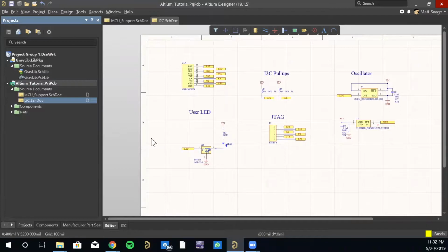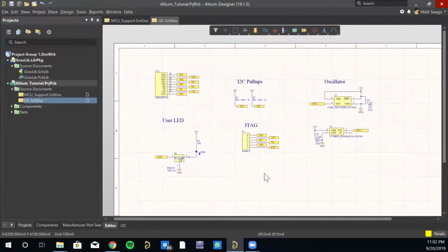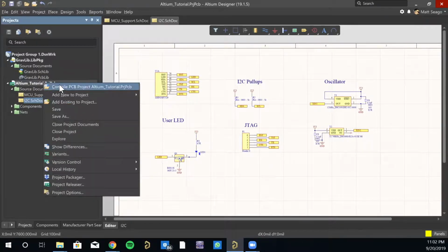So first thing we're going to do is I have added crystals. Be sure to check with your reference design on what crystals you need, where they go, what they're for, all that good stuff. Or maybe they're oscillators. There is a difference between crystals and oscillators. We're not going to get into that here, but just be aware of those things.